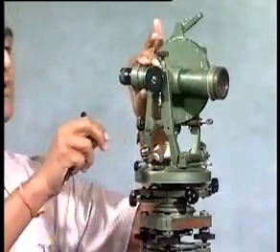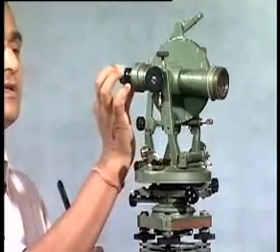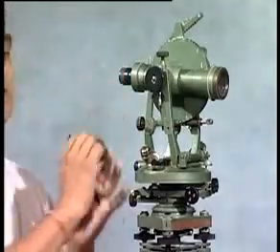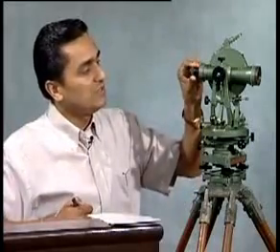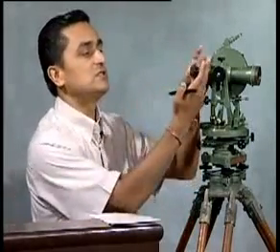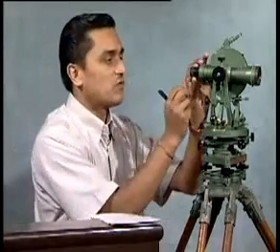Well, once it is so, I now focus the eyepiece. And this eyepiece needs to be focused because it will depend upon my eye. So if someone else is working, he will again need to focus it so that we can see the crosswire very distinctly. Once I have focused this eyepiece for my eyes, so I can see the crosswire very, very distinctly,